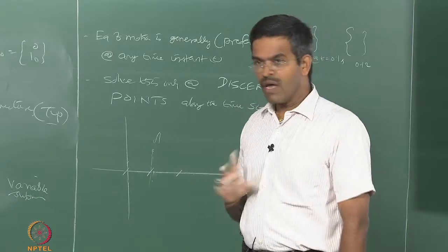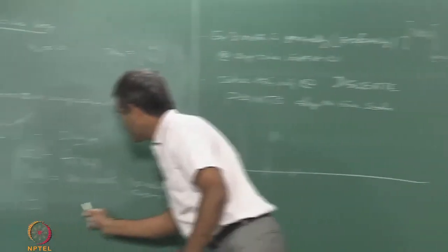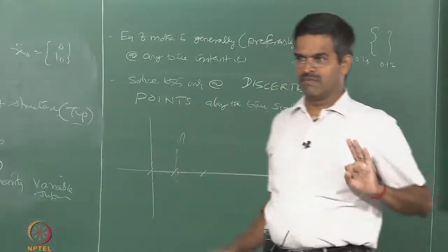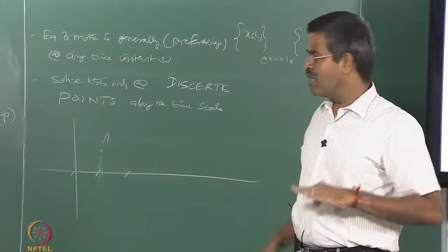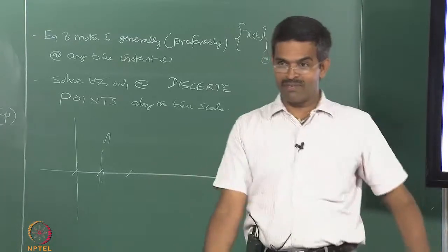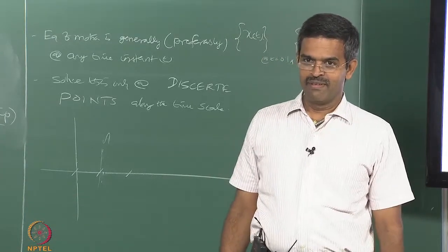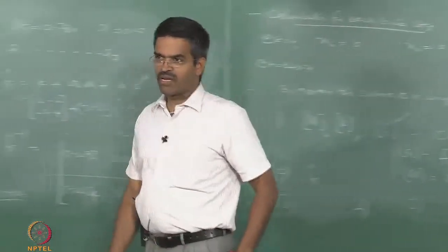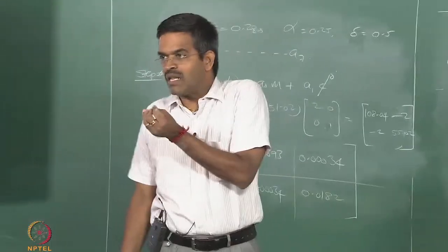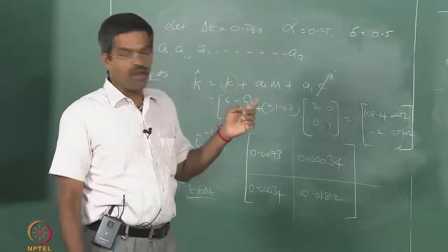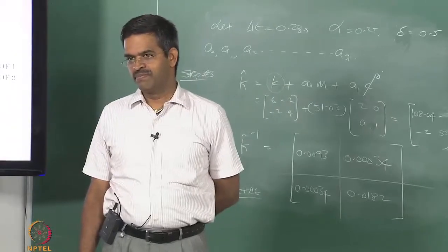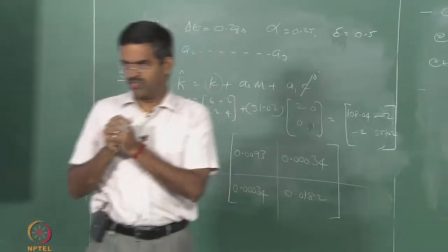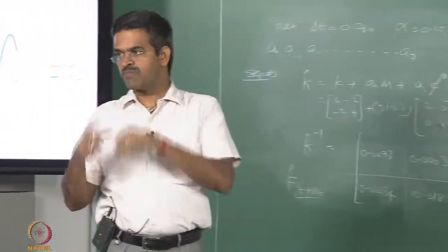Is it clear? And now the most important last confusion is, this convergence should happen at velocity, displacement and acceleration. Now there will always be a scheme where any one of them will converge, the other one will not converge. Okay. Therefore it is very difficult and complex that people do not apply this for compliant structures, and you will find very few analytical papers available on solving this by this procedure. Okay. So when your acceleration, velocity and displacement do not converge in the schemes, we focus on displacement.